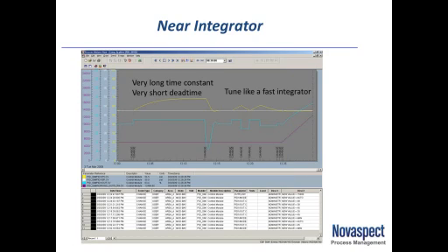But what if our process is such that the process itself filters out and removes all that high frequency noise? A good example of this would be if you're trying to control product composition and that flow is going through a large blender or mixing tank, or if we're doing pressure control of a very large volume, or even many temperature controls. That big volume, that big capacity filters out all the high frequency noise. So we don't have to worry anymore about being conservative and not magnifying it.